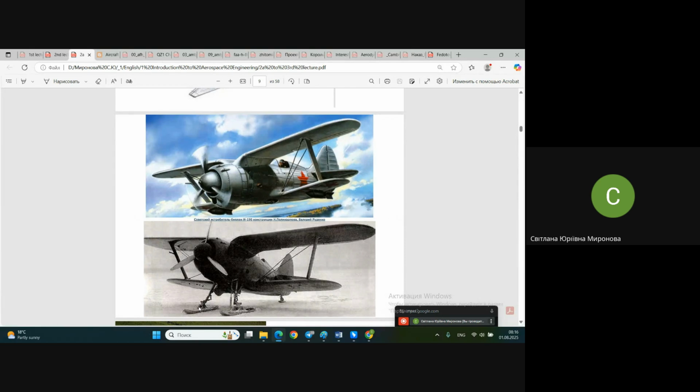And by the way, here it's visible what type of airplane it is, with three landing gears and a tail wheel. Landing gear with three legs and a tail wheel. Most typical for a modern airplane is a nose wheel. But why? If we come back to that photo of the An-140 passenger aircraft we just have seen, there is a place to hide the nose landing gear inside the airplane.